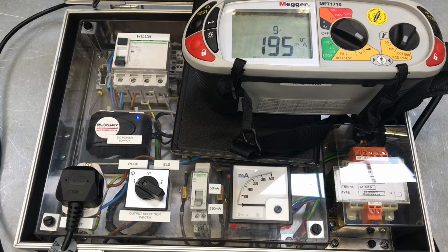Now, if you walk into a house and it's across the road from a railway station and it's a third railway, and there's no PV, then there's probably something being picked up onto the supply cable from the railway. But more than likely, it's going to be an EV or a PV, or even something as silly as a USB socket outlet where you fitted it onto a 25mm back box. The rectifier is cheap quality, it's got hot and melted, but sufficient just for DC to leak out the back of the rectifier, because these things don't switch off. I found that once. So my first video wasn't going to be about USBs, but it ended up being about USBs and sockets. So there you go.